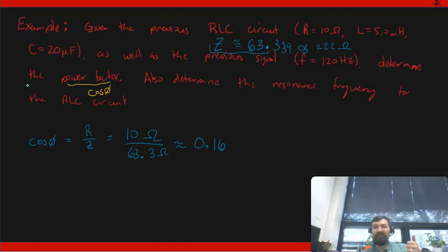So I either have a large capacitive reactance or a large inductive reactance, or both, compared to the resistor, and so very little power would be dissipated. So this power factor is basically telling us what fraction of the possible power that could be dissipated is actually being dissipated.